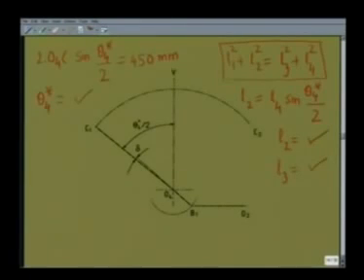To obtain the required value of delta, with the new lengths L2, L3, with L1 and L4 unchanged, I again obtained the path of B, which is this circle, and O2 B1 as we know was L3 minus L2. So, from O2 I draw a circular arc O2 B1 as L3 minus L2. So, I get the extreme position O4 B1, and the extreme position O4 C1 is already known.